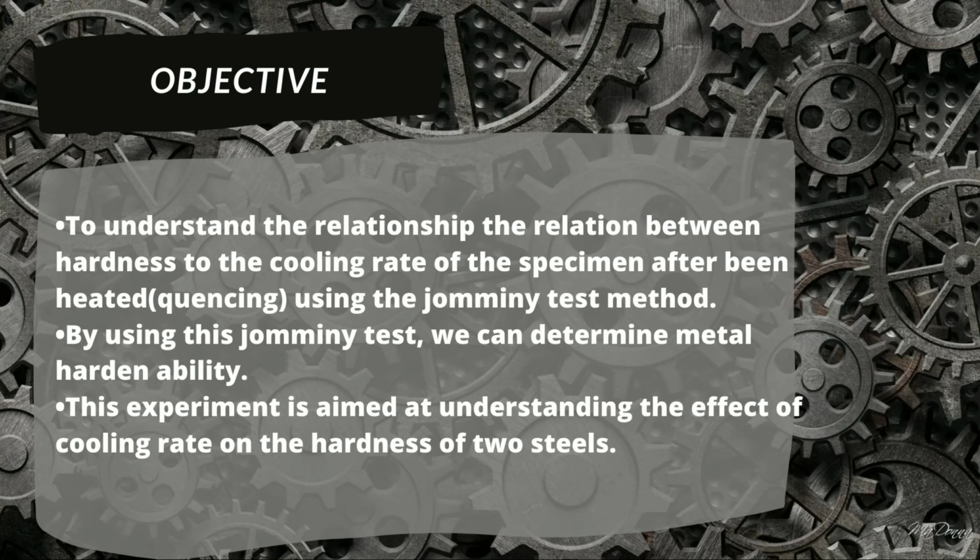So for the objective, first, to understand the relationship between the hardness and the cooling rate of the specimen after being heated using the Jominy test method. Second, by using this Jominy test, we can determine metal hardenability. Third, this experiment is aimed at understanding the effect of cooling rate on the hardness of the steels.